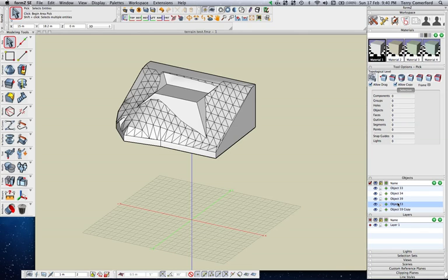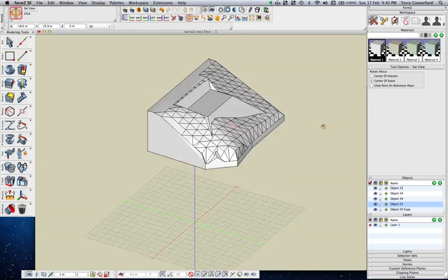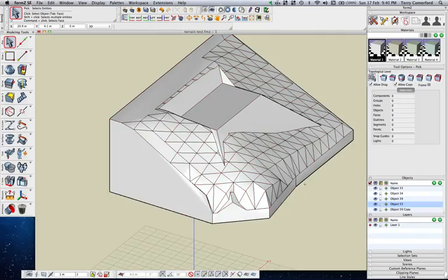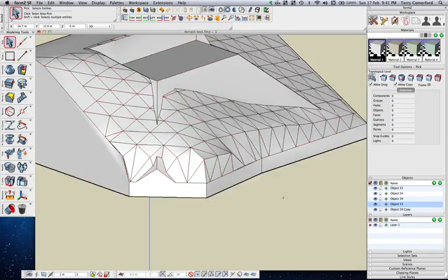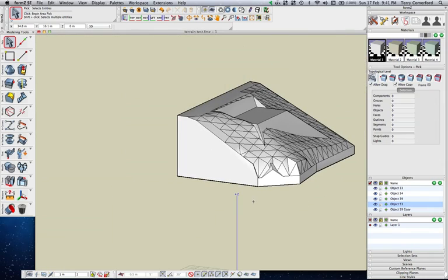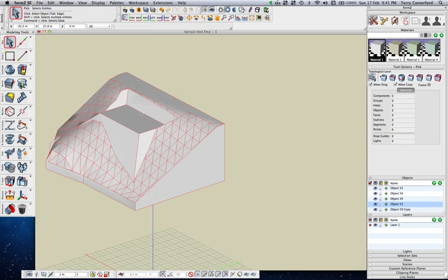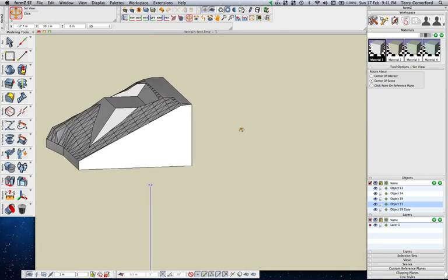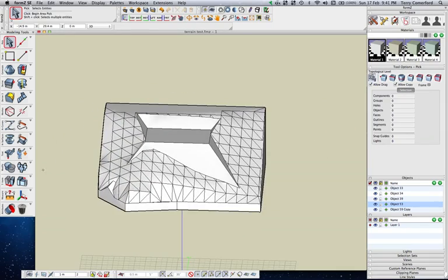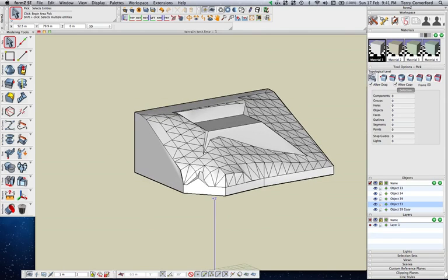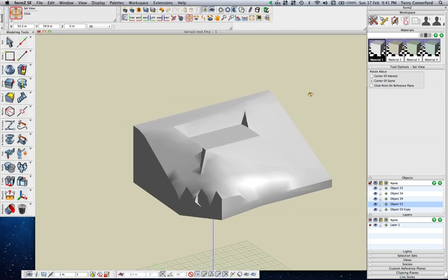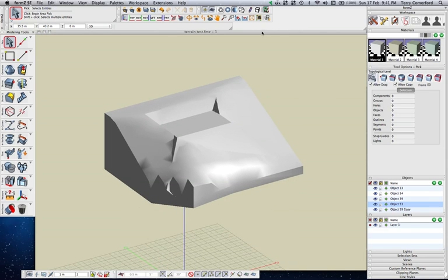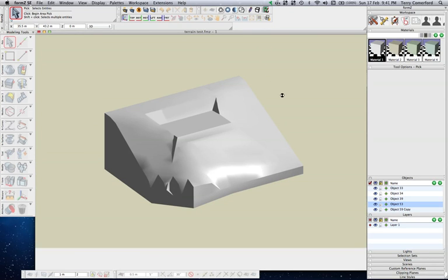It looks like I've deleted everything there now, so I'm left with a fairly clean terrain model that has a flat platform built onto it, and it has a fill batter at a controlled slope of 1-in-1 or 45 degrees, and it has a cut batter at a controlled slope of 1-in-1 or 45 degrees. So then we could change probably to a different view, so we can get some different appreciations and apply materials, of course, however you wanted to display that.